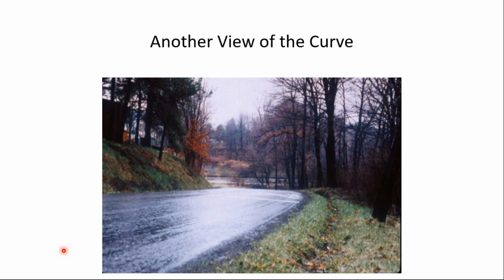And I think there was another deficiency with the roadway. I think you can see that even without resorting to any roadway plans or anything. Can you see that this curve has a negative or reverse or adverse super elevation? It's banked in the wrong direction. And this is one of those roads I talked about, I think, on the first day we met, where I said a lot of these local roads were never designed.